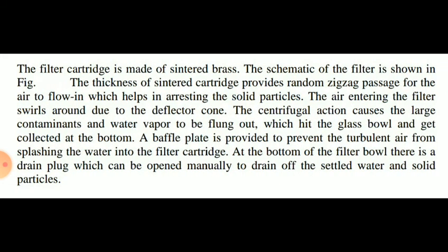The air cartridge is made of sintered brass. The thickness of the sintered cartridge provides a random zigzag passage for the air to flow in, which helps in arresting the solid particles. The air entering the filter swirls around due to the deflector cone. The centrifugal action causes the large contaminants and water vapor to be flung out, which hit the glass bowl and get collected at the bottom.